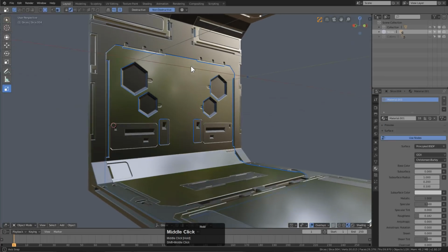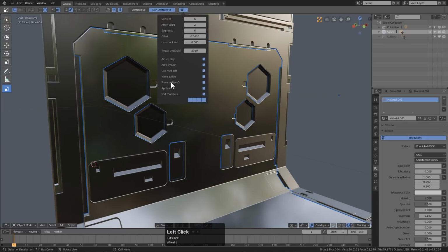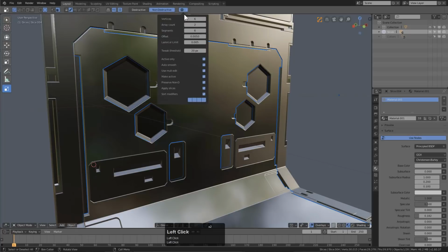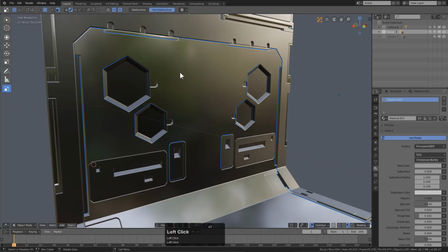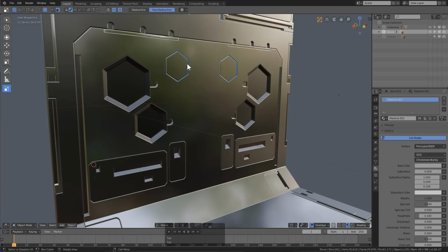Before we begin, I want to show you a couple of features new to Boxcutter 707. For example, in the behavior panel there is now an option for apply slices. So we have our circle, we're set to red, and our segment count is actually set to 6. So whenever we draw it out, it's going to create a pattern like this. And we bring that back, press X in order to turn it into a yellow box, and we click to apply. And if we look at this, the first slice has been applied, giving us exactly what we need here as far as allowing us to quickly get to work on this without it being a duplicate of the entire mesh.